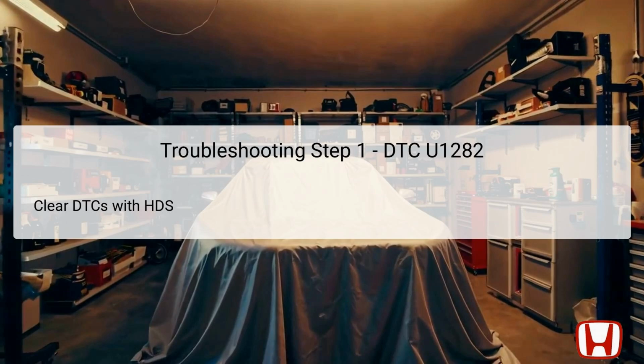The first step in troubleshooting DTC U1282 is to clear the diagnostic trouble codes, DTCs, using the Honda Diagnostic System, HDS. This tool allows technicians to erase existing codes, resetting the vehicle's computer, and ensuring a clean slate for further diagnostics. It's crucial to perform this action because lingering codes can cloud the diagnostic process and lead to misdiagnosis of issues.